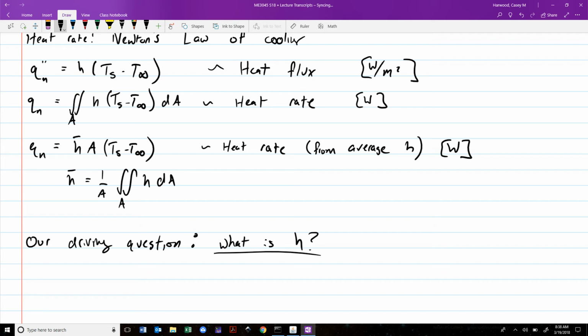it plays here, is that it's a region of transition between the value at that surface and the value in the fluid. Okay? So in the thermal boundary layer, you have this curvature that describes the temperature variation between the surface temperature and the fluid temperature in the free stream. Same thing for the velocity. And if we're dealing with this problem of species transport, where you have concentrations of matter, then you'll have a concentration boundary layer as well.